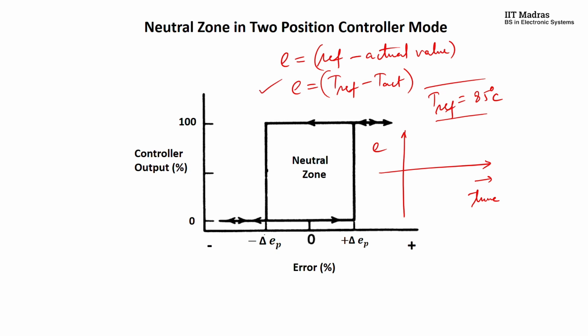Once we use the hot water downstream, the cold water enters the heater. Therefore the temperature goes up and down because of the heating and the cooling effect of the incoming and outgoing flow. So the error would slightly go up and down like this. Instantaneously you can see that the error would oscillate up and down around the zero value.